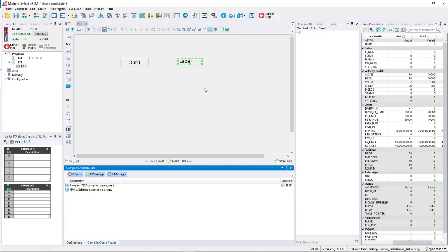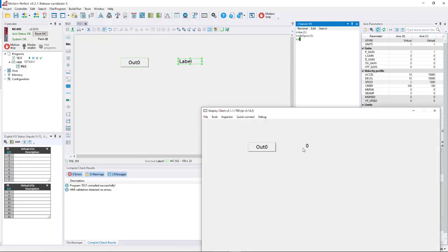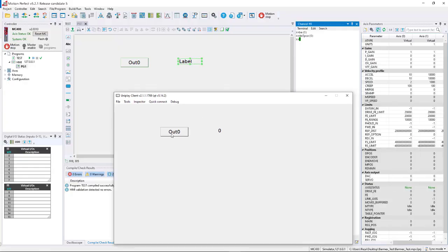And that's it. Then again, compile it. Let's choose base 0, and let's DEFPOS 0, so we reset the current position just to make a fresh start. Then if I open up the offline simulator, it will show a number and also a button. Once I activate the button, you see exactly the MPOS reflected here for me.